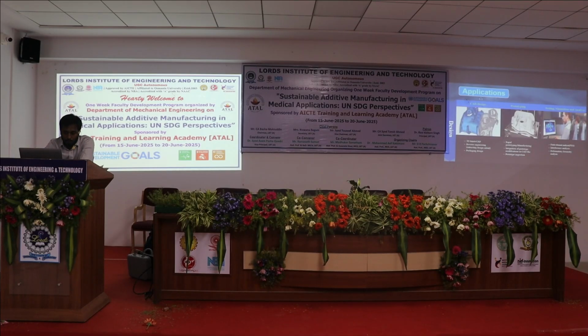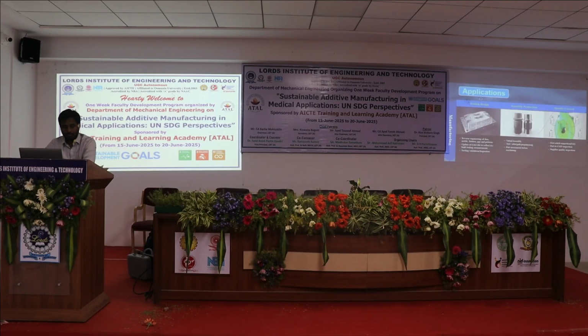Whatever this blue color component shows is scan data, and this gray color is the design data which comes from scan data. So mainly we use this reverse engineering for jigs and fixtures, dies, molds, and CAD files to reflect as-built tooling measurements.